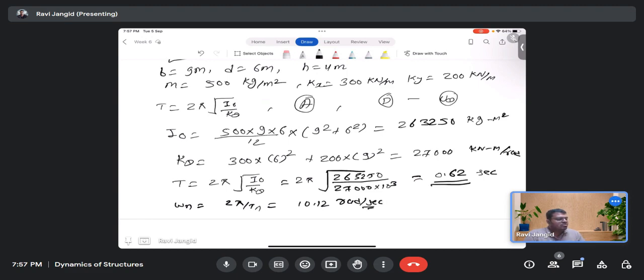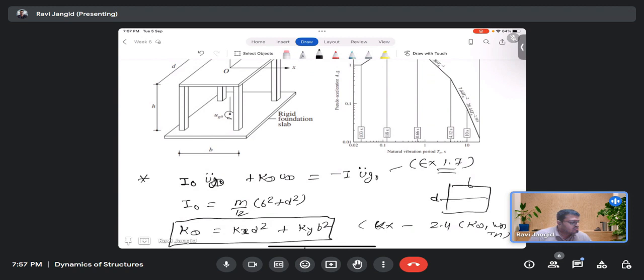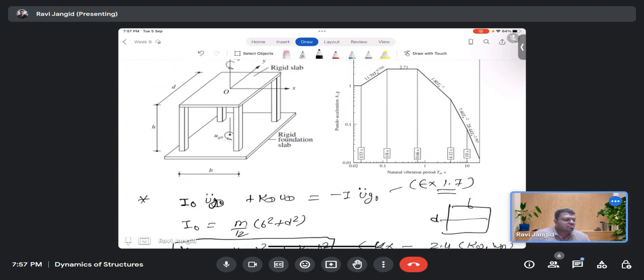Okay, now corresponding to 0.62, we can find out what our acceleration is. So here, that is lying in this range, that is constant 2.71. One second, 10 second is there, right? No, the bottom is logarithmic. So the time period is 1 by 8, 0.125. For 0.125 to 0.6 we have the 2.71.